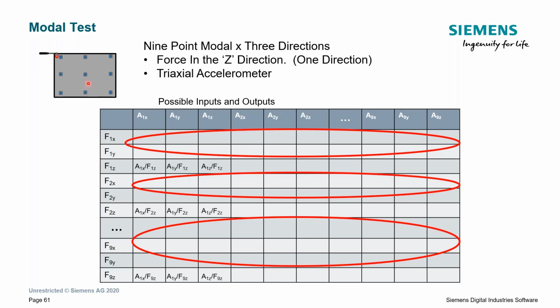Now, the problem with that is once I get, say, to this point 5, I can easily hit in the Z direction, but there's no easy way to hit in the X or Y unless I add some kind of post. If I add a post, I've changed the mass and the stiffness of my structure because I've had to weld or bolt something there. And I've also added this mass in the middle of my structure. So I've already changed my structure.